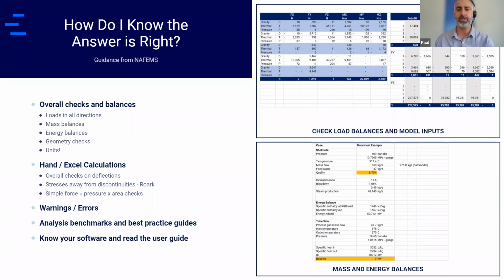application area. The first thing is that it's really easy to just say, okay, I've built a model, put all my loads into my model, I get a result, and it looks interesting, it looks good. So then what do you do now? The first habit I've always gotten into is checking the loads in all directions. When I first started, I spent a lot of time using Nastran. I remember Nastran had a great little O-load output, so that by default, it would give you a list for every load case that you'd run, what the reactions were, or the total balance of all the forces.